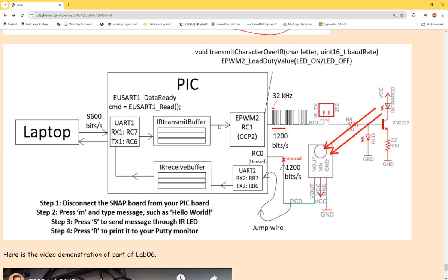And then when we are doing the transmission, you use the index to take out 1 by 1. You take 1 character, and it's a byte, and use the mask to extract every single bit, so you'll know what kind of PWM you want to send through RC1. Then this one is sending byte by byte, and this is receiving it, and you are using a certain baud rate, which is 1200. Why 1200? Since you already hard-coded it here.